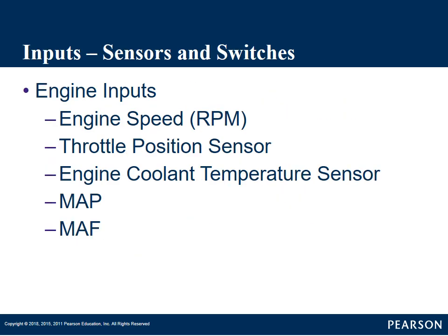Inputs on our transmission for our transmission control module. First, we have our engine inputs. Something I'll bring back up when we are talking about diagnosis. Always diagnose your engine first.